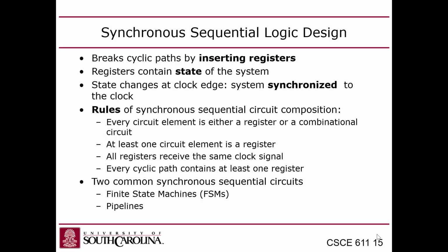And in the simulator, if you do that, ModelSim will hang. It'll just freeze. And then you're in trouble because there's no recourse at that point. There's no good way to debug that aside from commenting out half your code and seeing if that resolves it. And if it does, you know that wherever the problem is, it was in the half that you commented out, right?